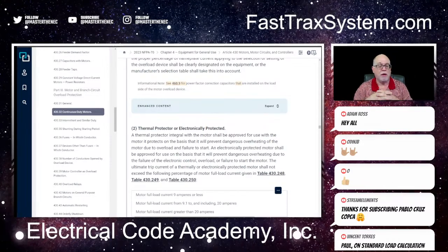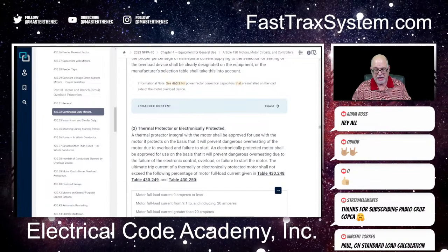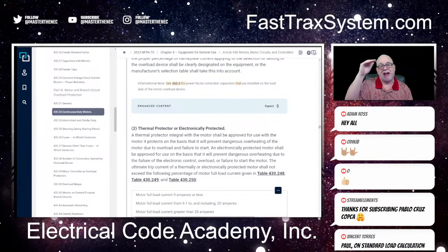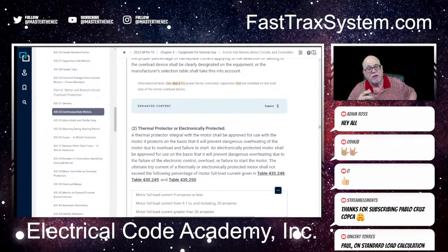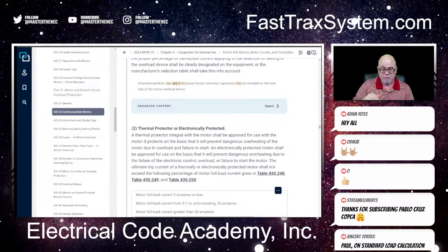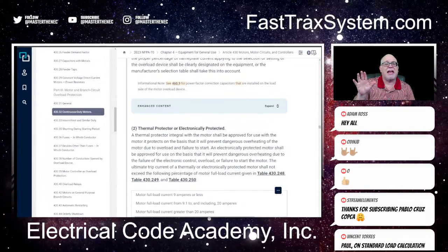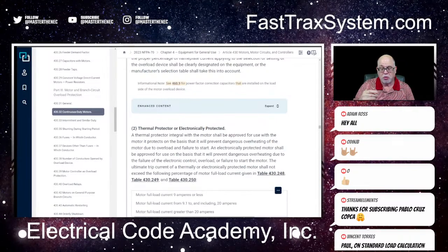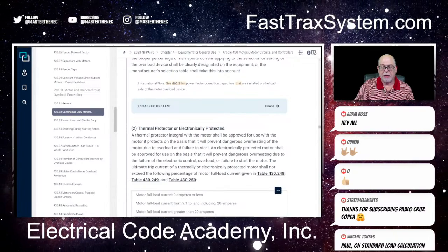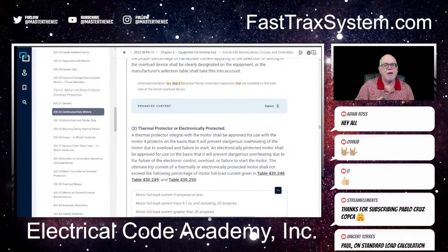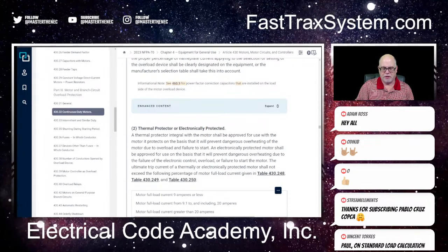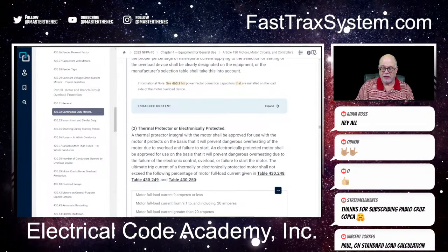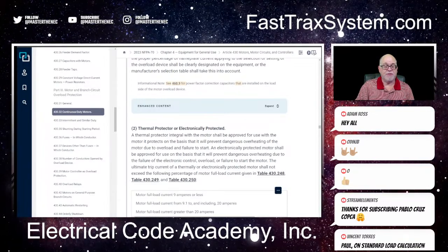Now, one of the things to remember, as with anything, the 8,000 watts is what we get from 220.55 in Column C for one range, as long as it's not over 12 kW. In most standard ranges like that, it's probably going to be fine. But if it's 50 amperes, for example, we're looking at 12,000 watts, roughly, divided by 240 is 50 amps.